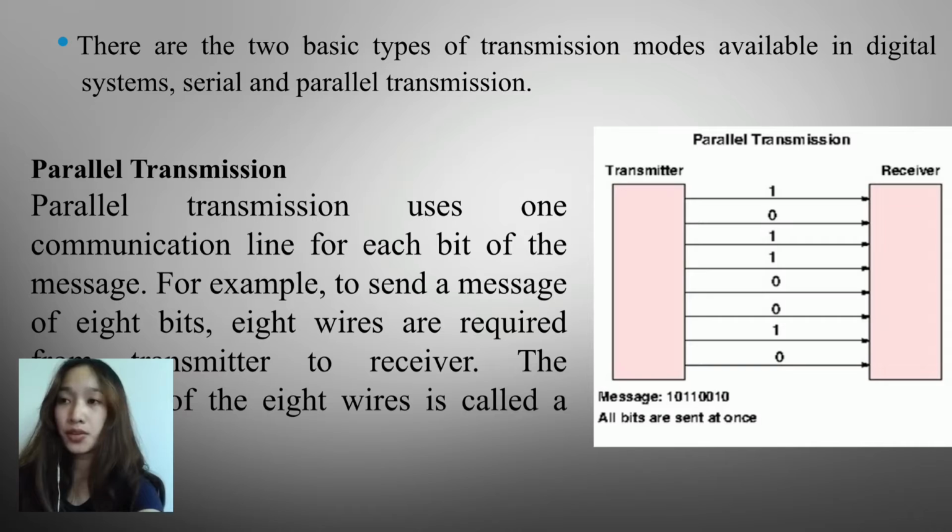Parallel transmission is normally used when the physical distance between the transmitter and the receiver is short, because it is difficult to maintain bit synchronization in long transmission. Typically, parallel transmission is preferred within a device. Communication pathways between the CPU and the memory of a computer are parallel. There are several protocols using parallel data transmission throughout the industry, including parallel PCI, ISA, ATA, and SCSI. The accompanying figure depicts transmission for an 8-bit message using a parallel bus.